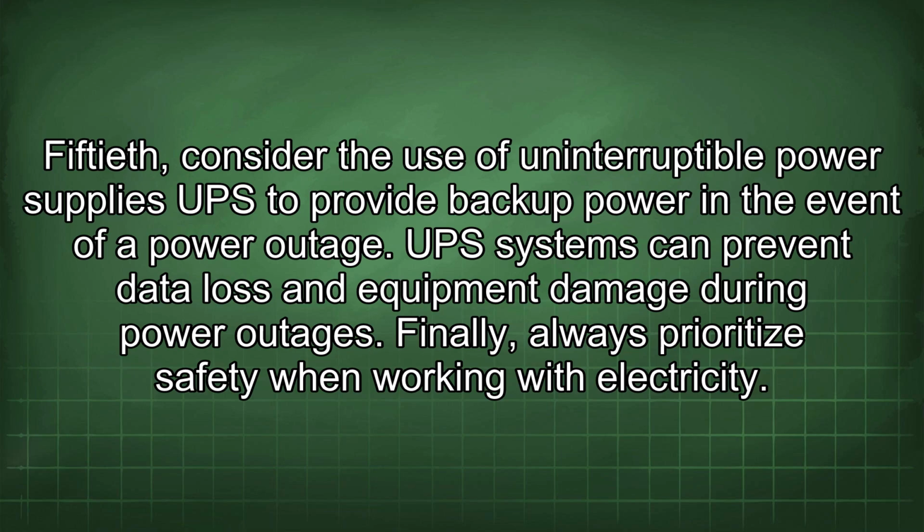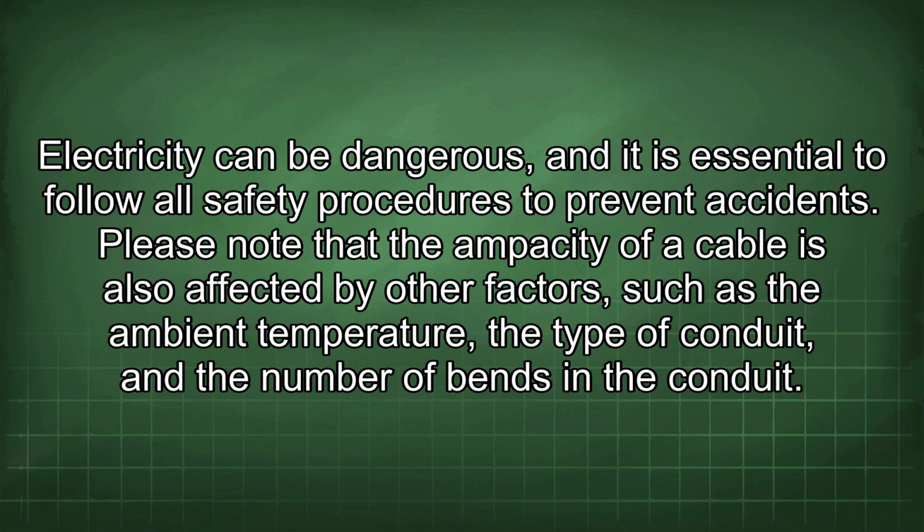Finally, always prioritize safety when working with electricity. Electricity can be dangerous, and it is essential to follow all safety procedures to prevent accidents. Please note that the ampacity of a cable is also affected by other factors, such as the ambient temperature, the type of conduit, and the number of bends in the conduit.